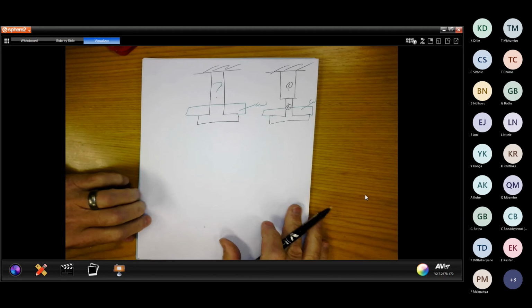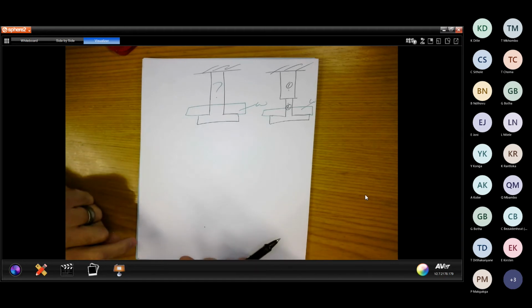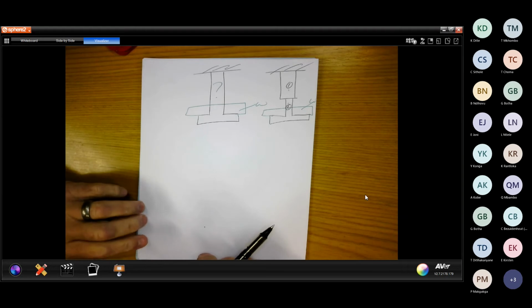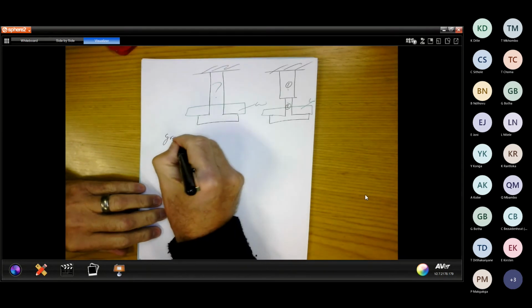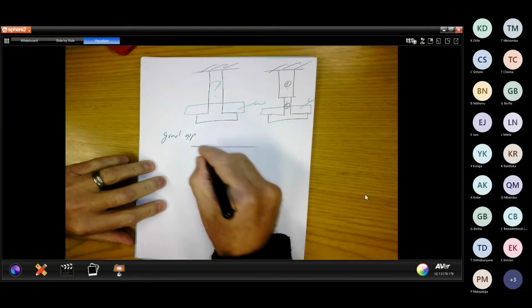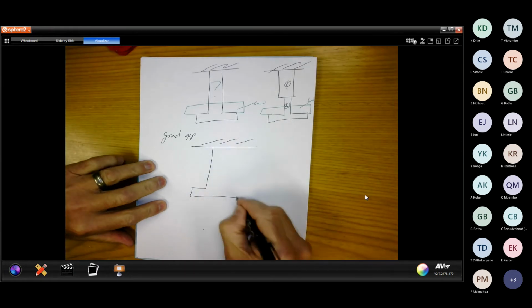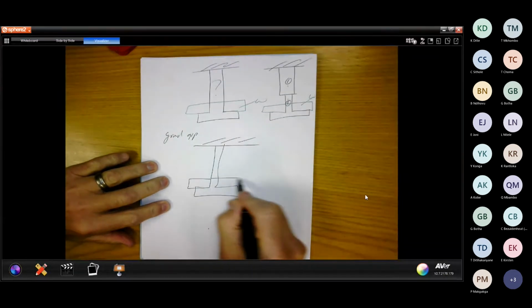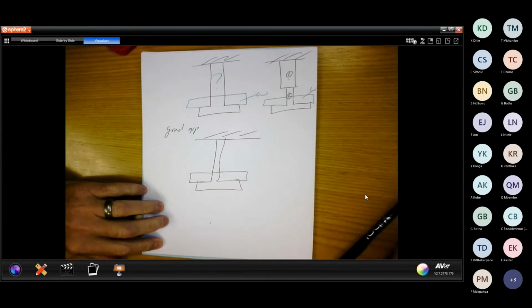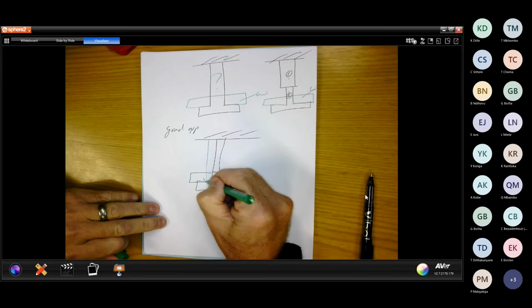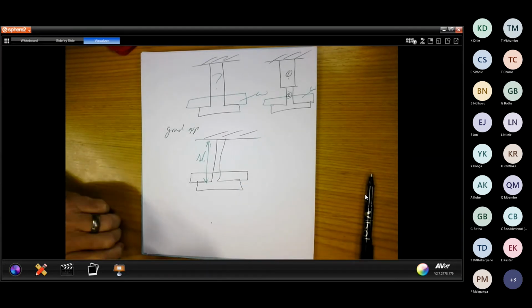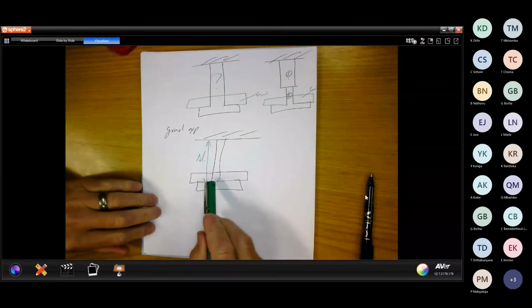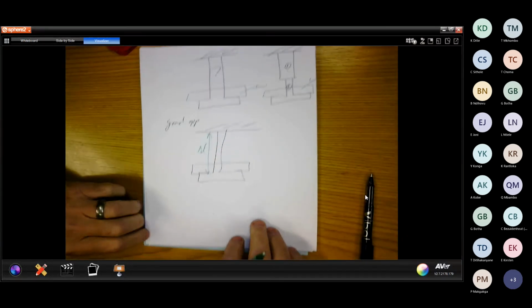All right. To come back to that, there are three conditions. The one condition is gradually applied. That means gradually applied is the one I drew for you the first time here. I have that, and I put on a load here. With my load, yes, there will be a change in my length, depending on my weight. But if I remove my weight, automatically my length will go back to its original length.